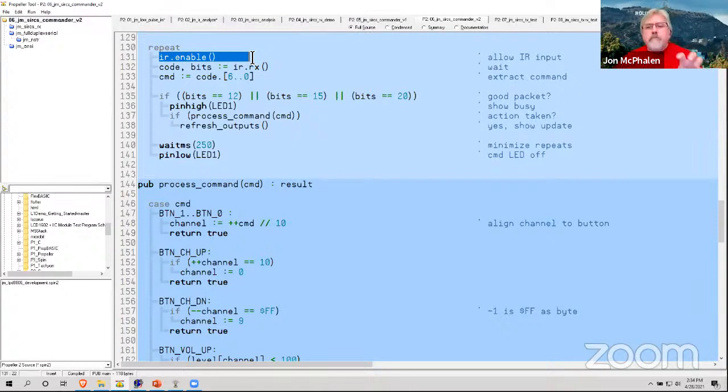Because of the way TV remotes work, I've not, in my experience, found it necessary to buffer multiple packets in. Once we get one, we know this is a slow process and there's going to be more of that, so we can ignore everything else till the master program has had time to process what we did receive.